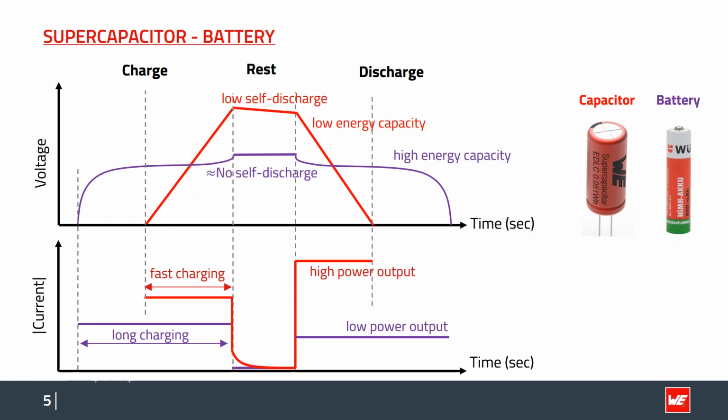Supercapacitors are capacitors, however not used for noise suppression or the smoothing of voltage. Supercapacitors are more like a temporary battery. This charge and discharge characteristic shown here illustrates the difference quite well, I hope. Since the supercapacitor is a capacitor, the voltage increases and decreases linearly if charged or discharged with a constant current. A battery does not. It has more a plateau-like voltage behavior.